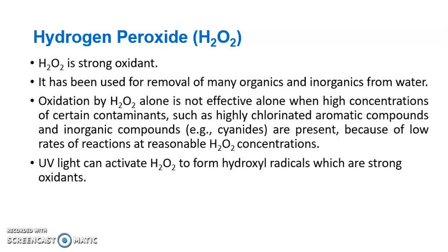So the reaction is much faster when we combine hydrogen peroxide with another oxidant like ozone or even with UV light irradiation, because when we are conducting the UV irradiation, basically it converts hydrogen peroxide to hydroxyl radicals, which are much stronger oxidants compared to the hydrogen peroxide.